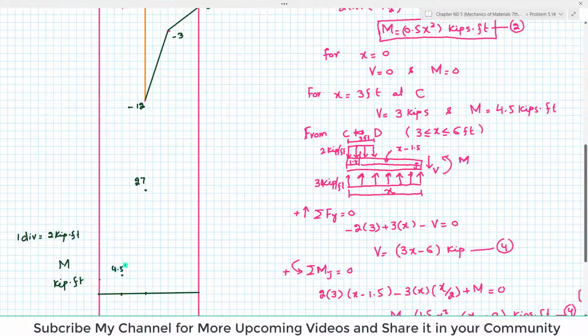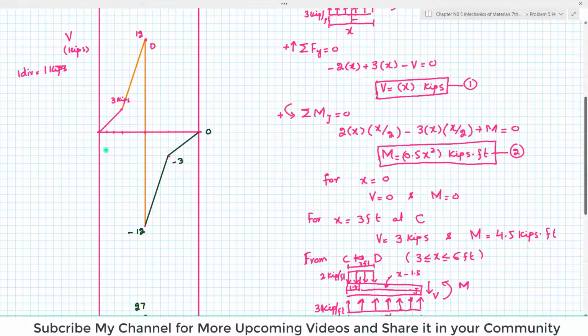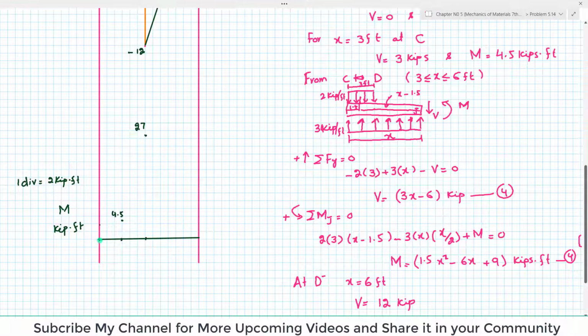This is 4.5. So what you can see is that all the slopes of shear force are positive, moving upward here. So bending moment will be a second degree curve and it will be counterclockwise. You have to join them like this here, and similarly here again at a distance of 9 feet it will be 4.5. So it will be the same, counterclockwise. You have to draw the curve. I'm trying my best, but it is a second degree curve and it will be counterclockwise, and it will be equal to 0.